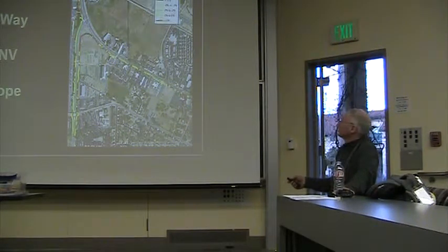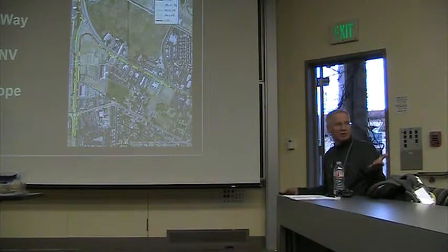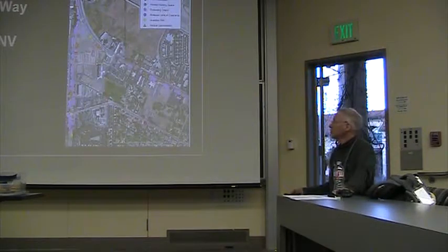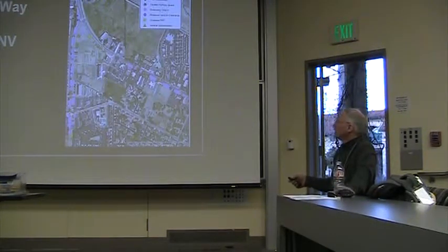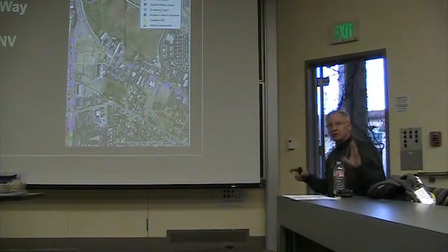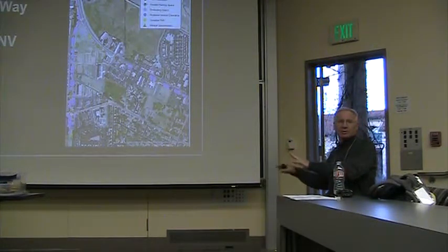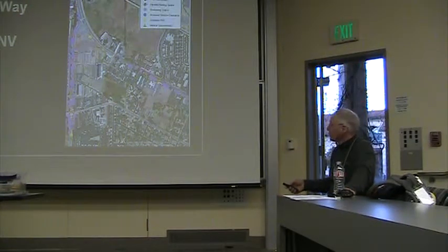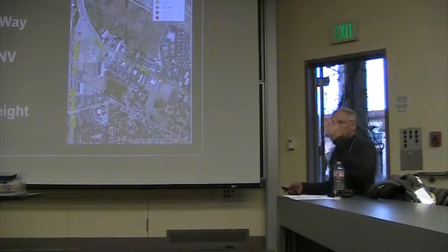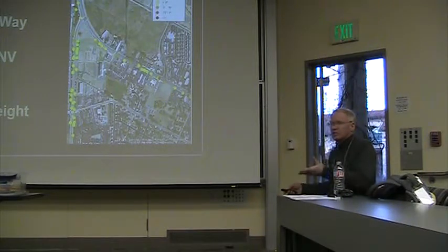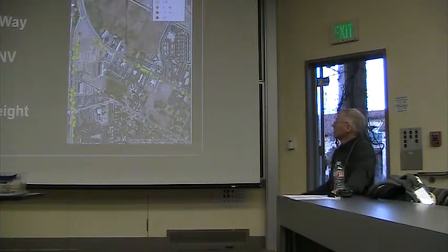Or in this case, we're showing how much cross slope there is. So all the red is greater than 5% cross slope. The yellow is 2 to 5%, because it's supposed to be less than 2% cross slope sidewalk. So we can real quickly go out and measure all these different obstacles and obstructions, and then they all get fed right into layers in GIS maps of cities, so that they can see exactly, and they can create reports of the sidewalks that need to go out and grind and whatnot.